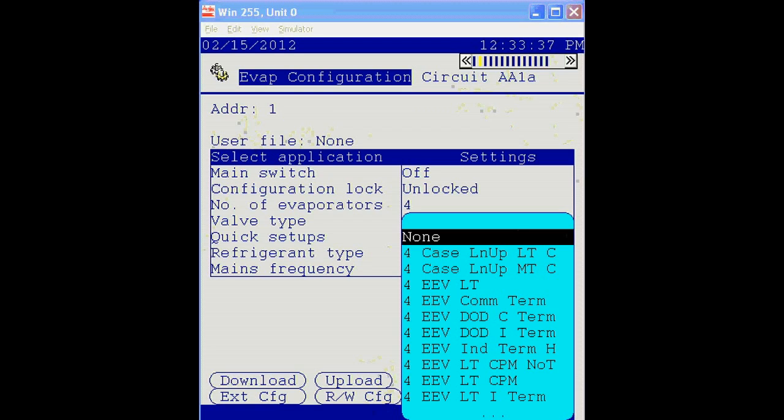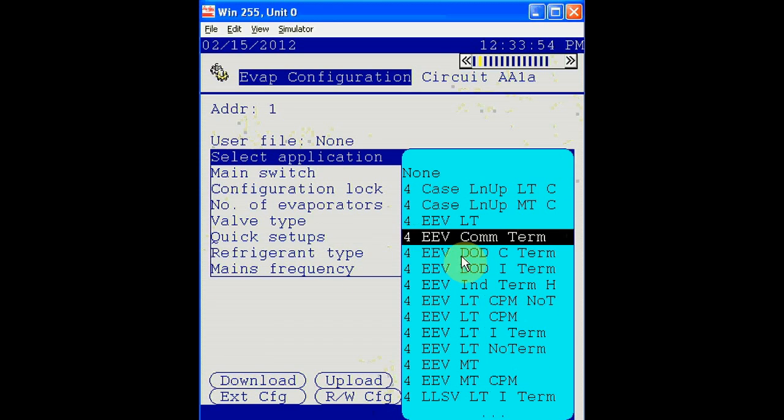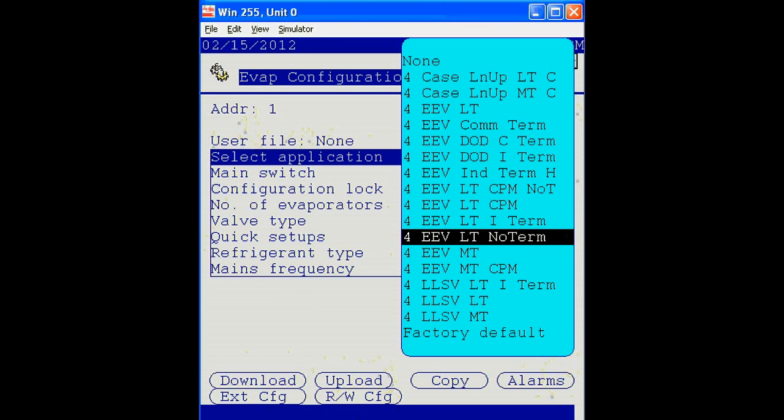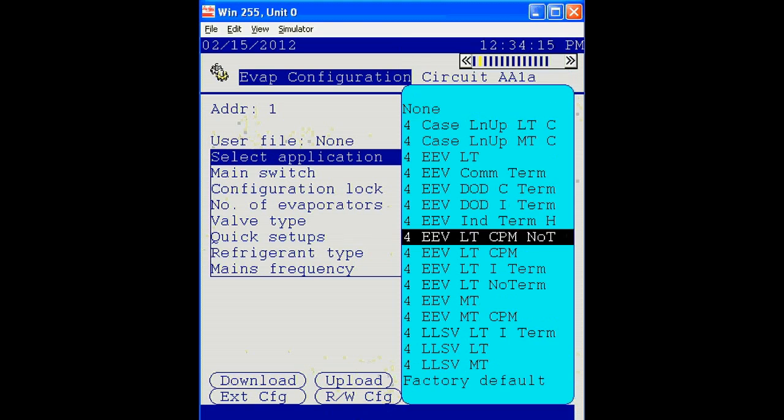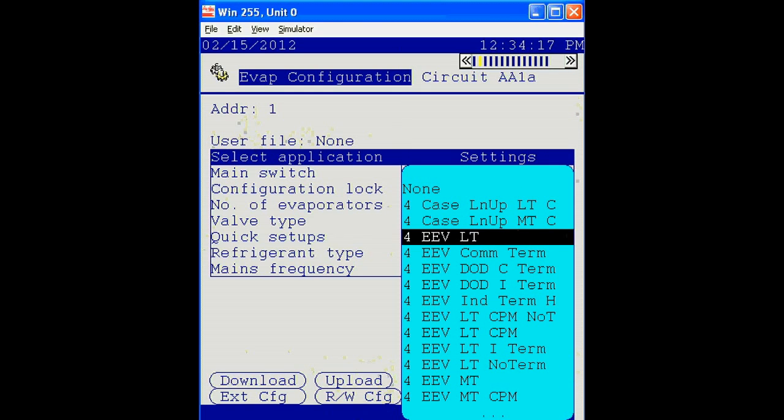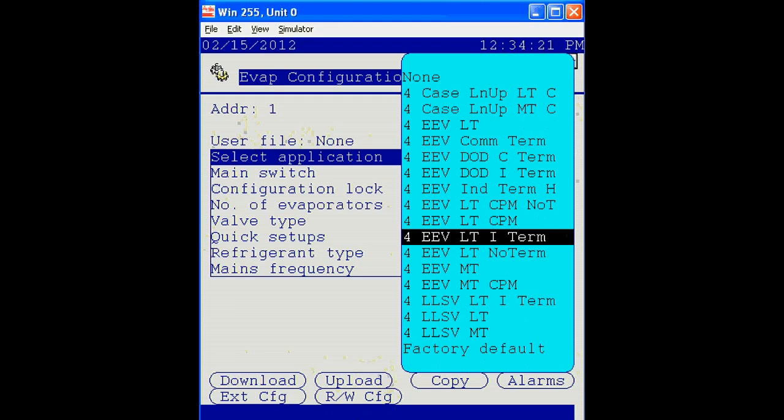If the board and points of the sensors and relays have already been assigned through the service tool, you will not want to make any selections here. However, if the layout of the sensors and relays has been done in such a way that it matches up with one of the quick setups here, that does not require the service tool, and allows for a single choice to be made that will assign all the board points at one time. The user would have to know what each setting for the quick setup corresponds to in regards to the I/O layout before making this selection.